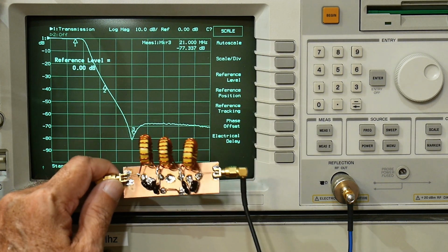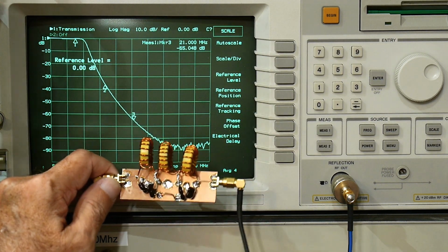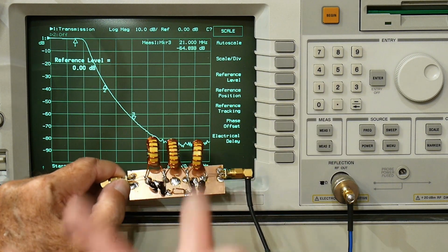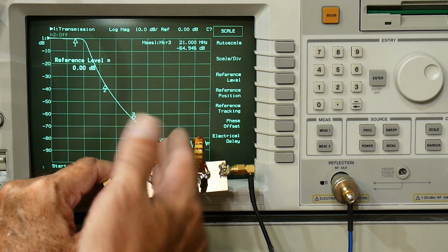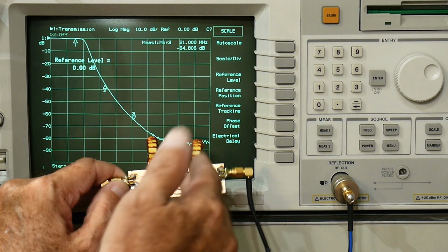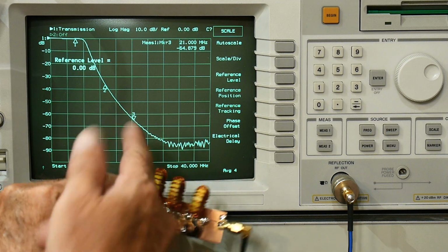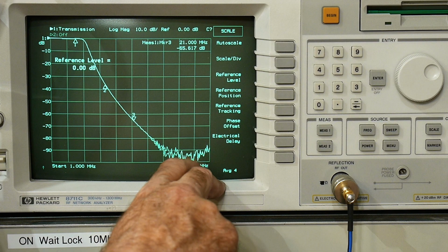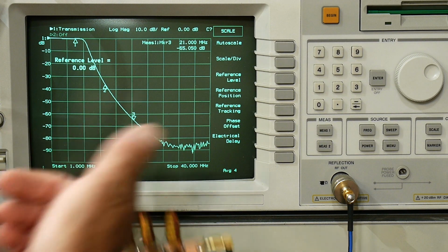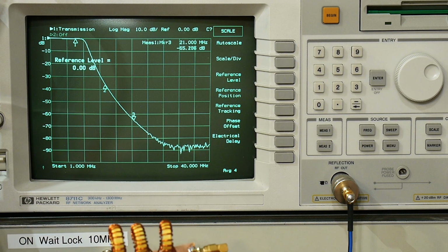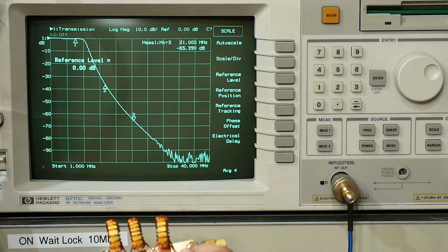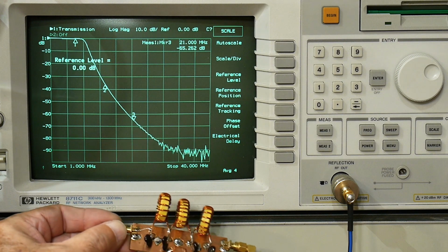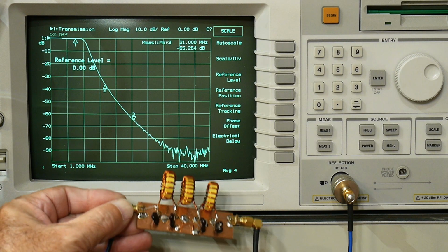So there's a lot of mechanical things that you can do in order to make filters better. You can look at that online. There's tons of filters you can see, and a lot of times they're made with PC board dividers between the different sections and stuff. And that is to get rid of this crosstalk. And you can see that we increased this filter by 10 dB just by making sure that the capacitors weren't right next to each other. So there you go.